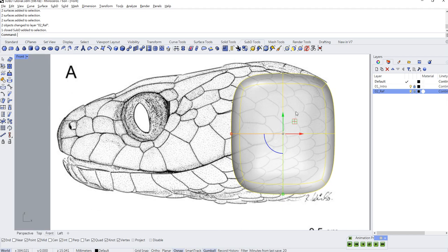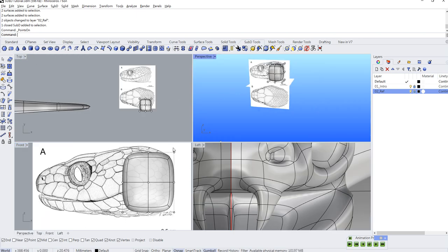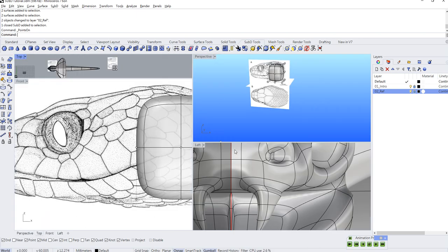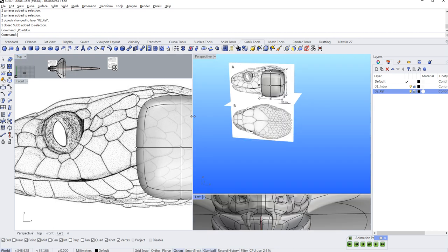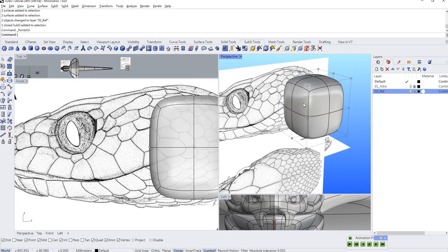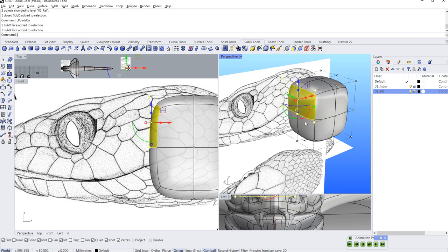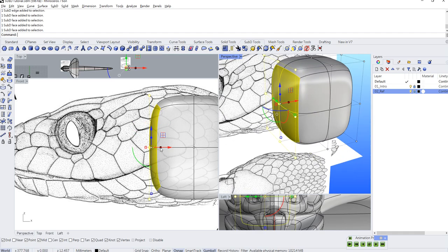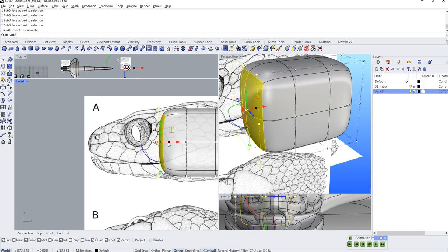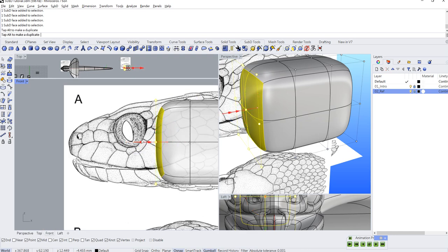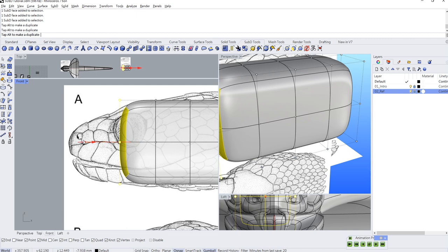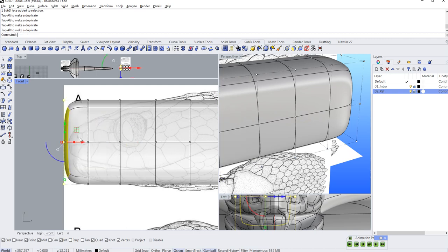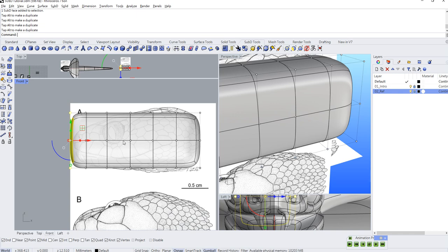First thing is let's press F10, go to edit mode, and I'm going to select the face. We can change the size right here. Okay, so let's select the face right here. Hold down your Shift and Control key, select all of them. Make sure you have selected the face, and then extrude. I think we can just base it on our intuition to do the extrusion. For now, I only extrude probably 4 sections.